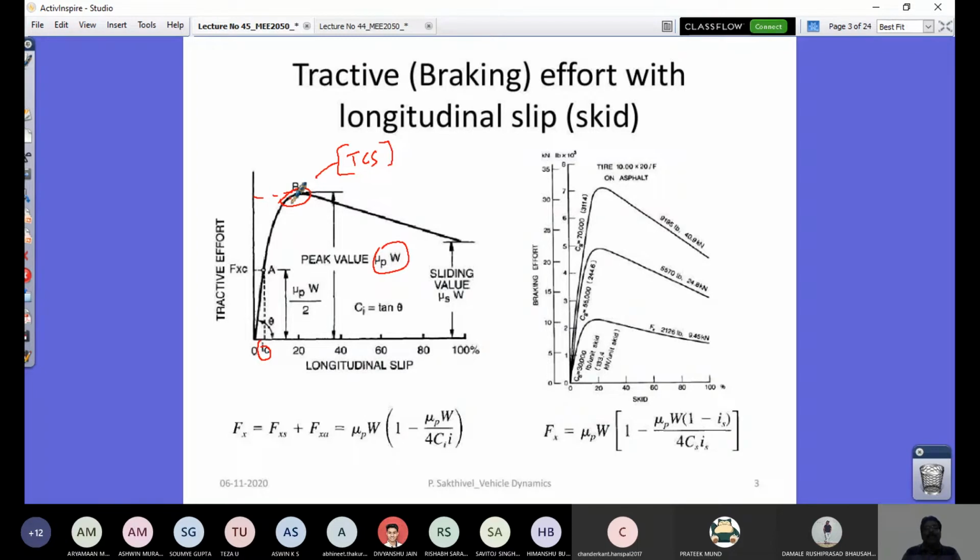The sliding is required to bring in this non-linearity, but that should not progress and cover your complete contact patch till the front of the contact patch. If it comes to this point, a smaller increment in i would also make your tire fall to a sliding value of your road coefficient. That is an important point here.